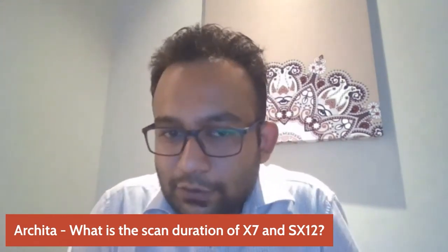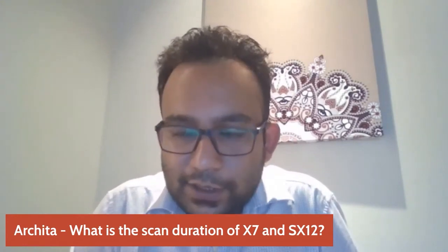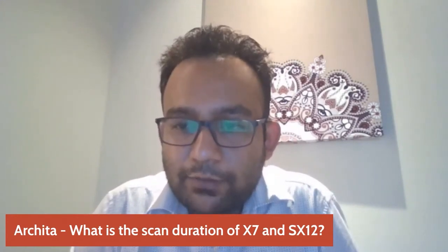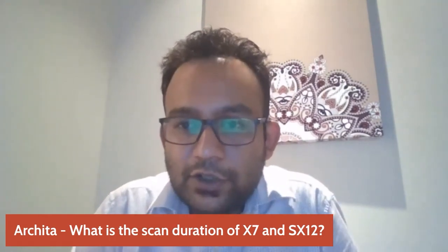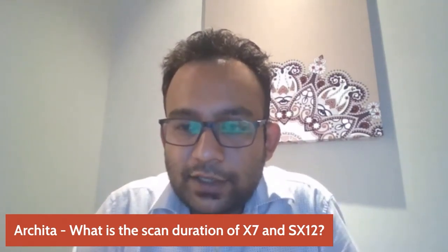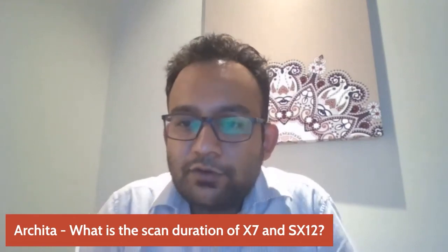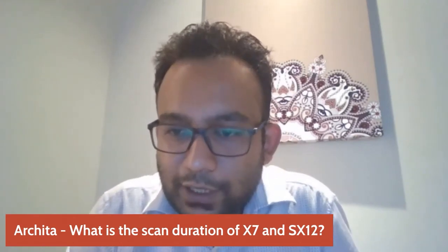When we talk of SX12, SX12 takes a lesser number of points as compared to X7, because it is a combination of a traditional total station and a laser scanner. And for SX12, the scan duration will go from 5 minutes all the way up to 1 hour.